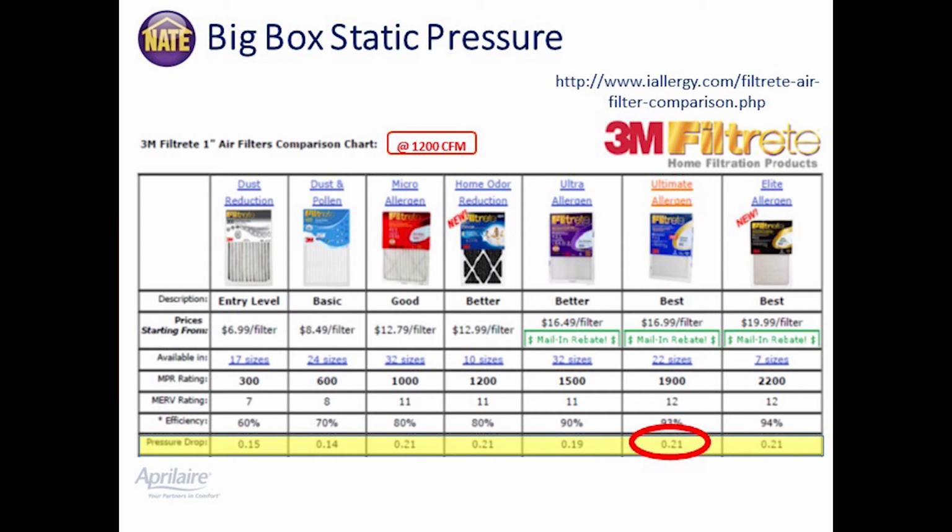It's a MERV 12, which is a good MERV rating. Static pressure is a little on the high side. But one of the reasons that people like to use these 1-inch filters, they say they're inexpensive, 17 bucks. But if you're changing that filter out every month or every 3 months, that's quite a bit of money. And remember, that 0.21 is the initial static pressure. If you're running a lot of, let's say, air conditioning calls, that particulate is going to build up in that little filter, and that static pressure is going to climb quite quickly.